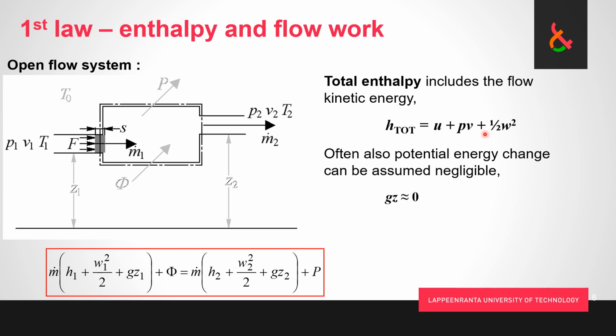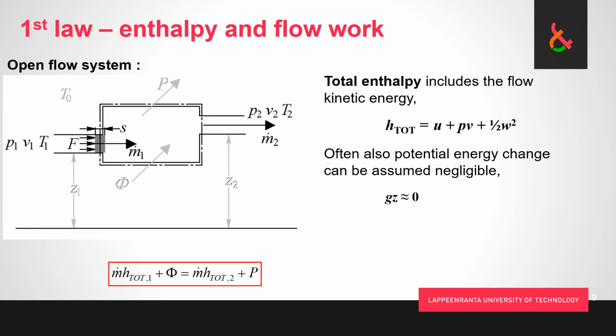This is because we're talking about thermodynamic cycles, power plant cycles, power cycles. So cycle means that you start from one point, you end up right back at it, even if the height from any zero level that we may define varies even quite a bit. In the end, it all balances. So we can say for purposes of calculation that potential energy change is negligible. And then this starts to look quite a bit simpler.